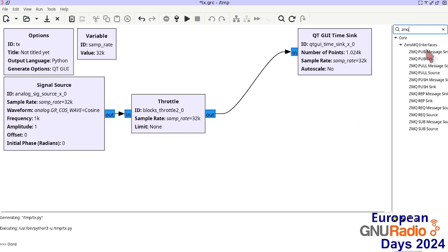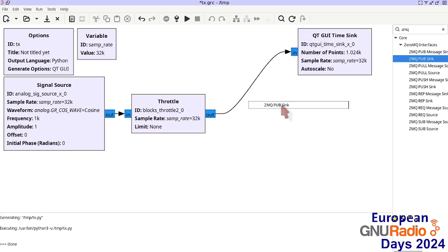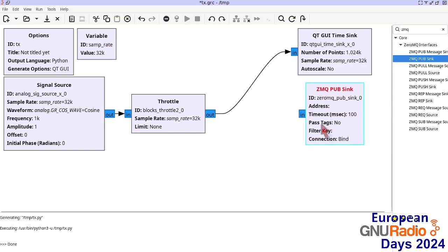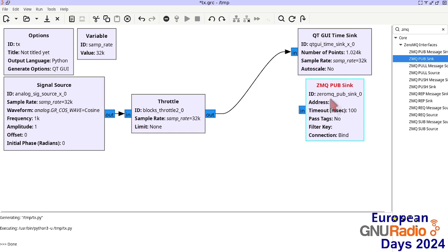We have two sets, the publish subscribe, pub sub. The publish subscribe framework is UDP-like, meaning that if someone is listening to the published data, it will be received. If no one is listening, too bad, it's lost. And that's exactly what we want for the radar application, where the antennas are moving, we don't want to record the data, but we don't want the SDR to stop collecting information.